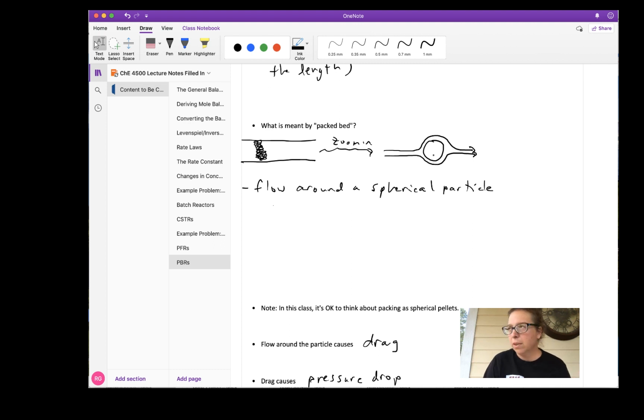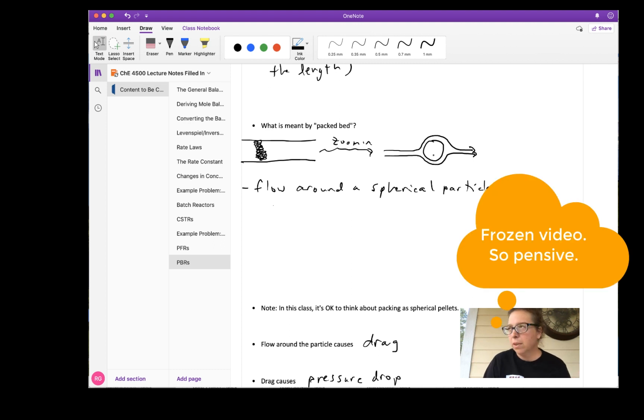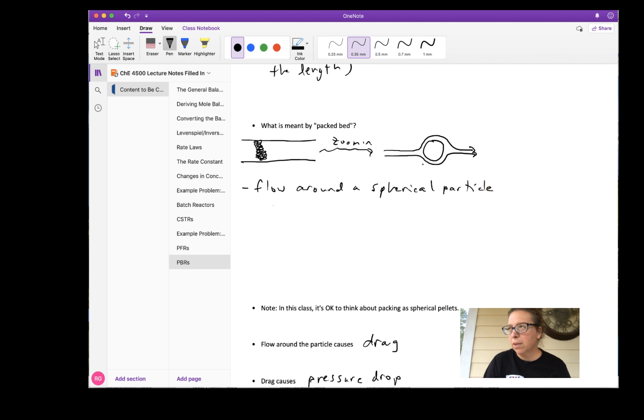Now, a catalyst is not identical to a sponge, but at least for illustrative purposes, the porosity works the same way. So the surface area inside this catalyst pellet is actually really large because of all the pores. There's probably hundreds of meters squared of surface area per gram of catalyst pellet. That's why most of the activity is going on inside the pores, because you've got a lot more surface area there. So for the catalyst to be active, gases are actually going to have to diffuse into this catalyst pellet so that they can contact the catalyst material there and react.